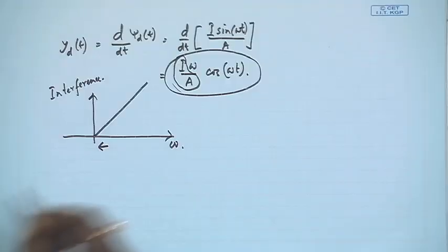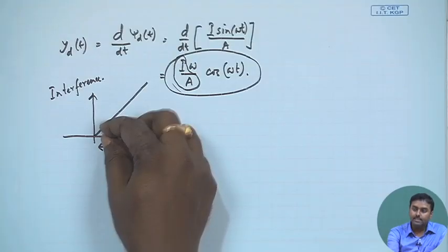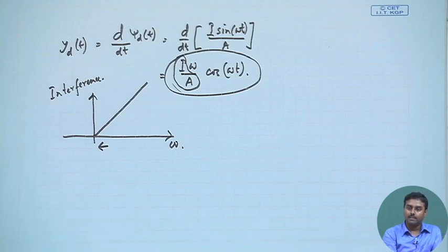So what we can see, as omega is closer, this is a very interesting thing, the interference term is smaller. As the interfering signal comes closer to you, you are more afraid that because the interference is closer, probably more interference I will be getting, but FM has a cancellation part. Due to its modulation and demodulation, it cancels that.